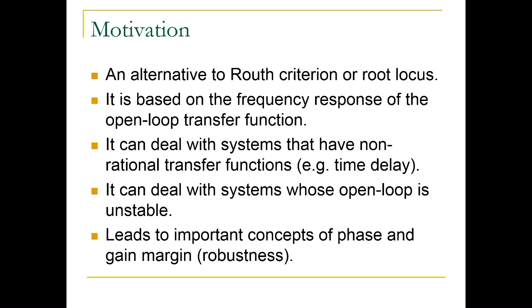And actually, Nyquist leads to these important concepts on phase and gain margins, but it leads to a lot of other concepts that are fundamental to frequency domain design. So loop shaping designs are basically based on concepts that come from Nyquist criterion. So we will introduce these concepts today.